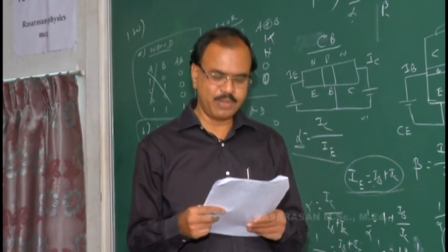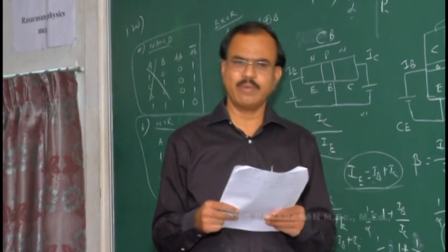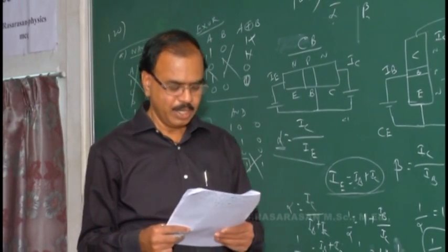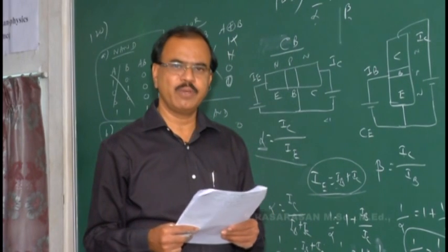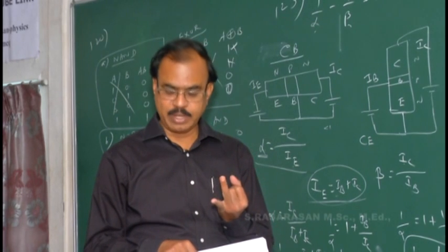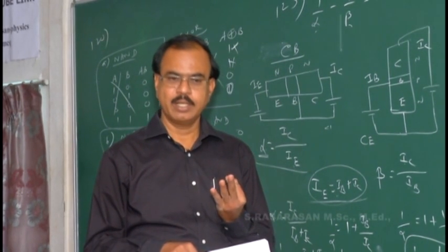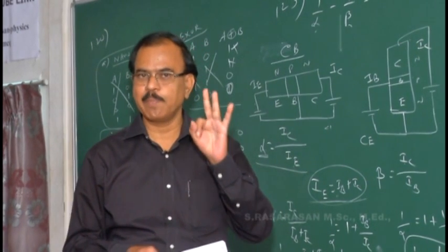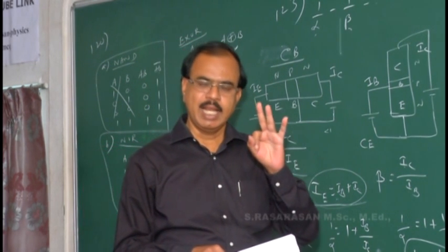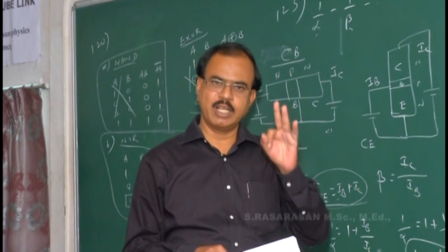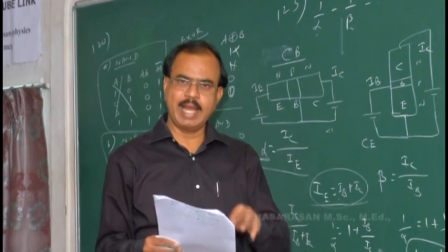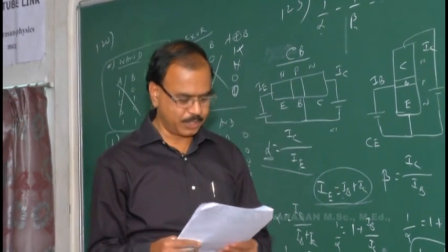So third option, an amplifier without feedback. No, in any amplifier we need feedback. Fourth option, amplifier with positive feedback. An oscillator is nothing but an amplifier with positive feedback. Recall, an oscillator has an LC circuit, amplifier circuit, feedback network. Feedback network is giving proper feedback, positive feedback. Without positive feedback, the oscillating waves produced in that oscillator cannot be maintained. We need positive feedback. Amplifier with positive feedback is an oscillator. So fourth option is correct.